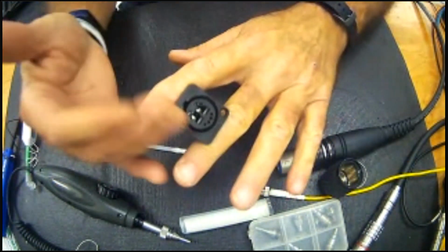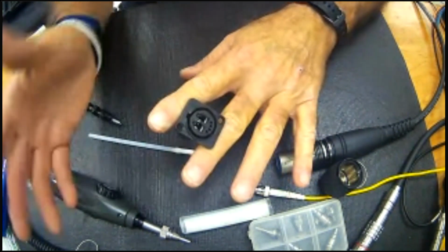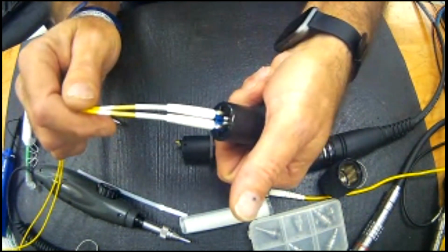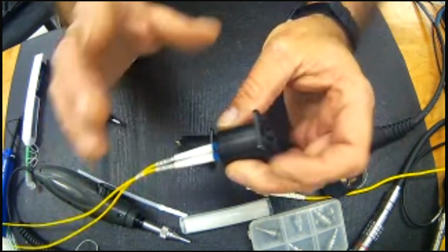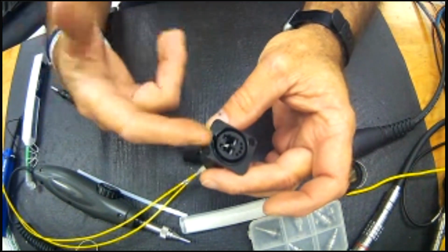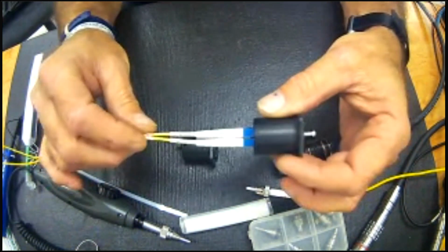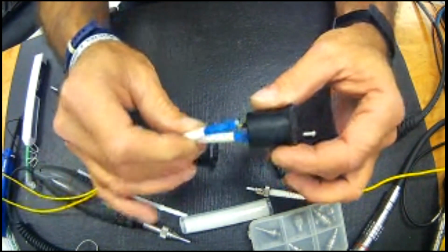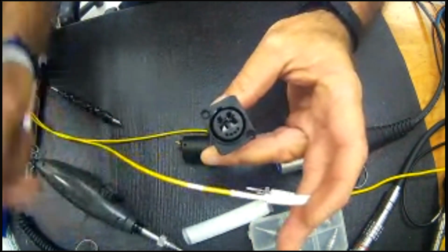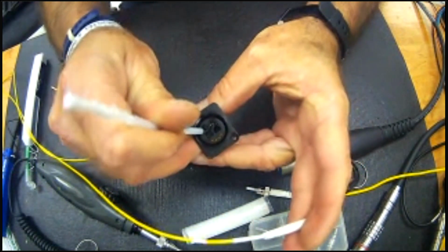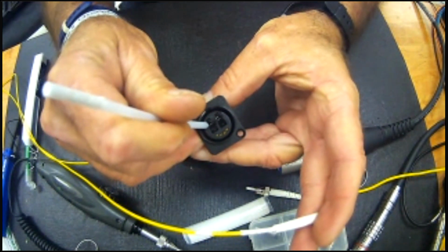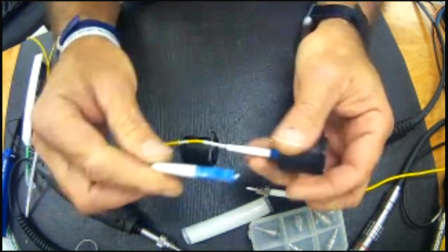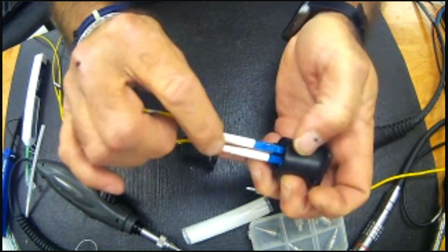The receptacle you're going to find on your cameras and on your CCUs, because there is no jack, is nothing more than a pair of LCs in the rear with some electricals attached. The equipment that I personally have taken apart, I was able to pull the two screws off and goose the cable forward just enough to be able to extract those contacts. I was able to service those contacts. The other option is to retract that insert and try to work through alignment sleeves. I'm not a big fan of sticking Q-tips or other type of debris through alignment sleeves if I can help it. I would prefer to actually work the surface of the contact and reinstall them.